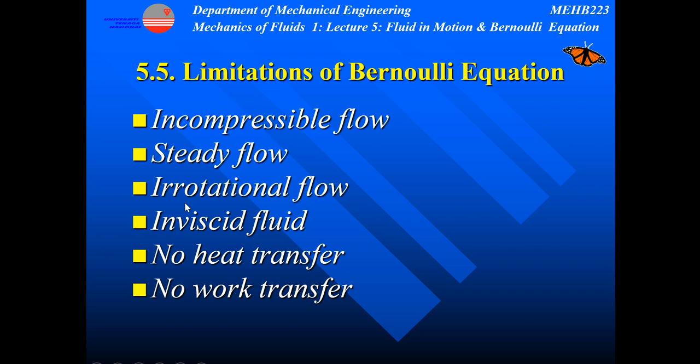There are some cases where the flow becomes rotational, and for that you cannot use Bernoulli equation. And it has to be inviscid fluid, meaning no viscosity. That's why you can have slip at the boundary. Velocity is constant. And no heat transfer, no work transfer. If there is heat and work transfer, then you have to use another equation, which is the energy equation.